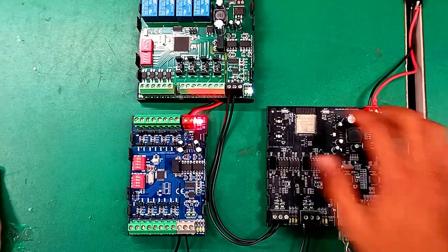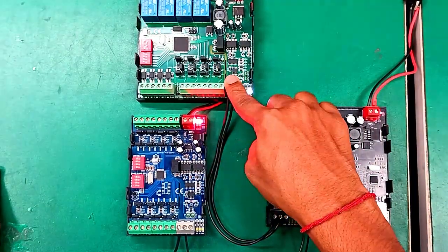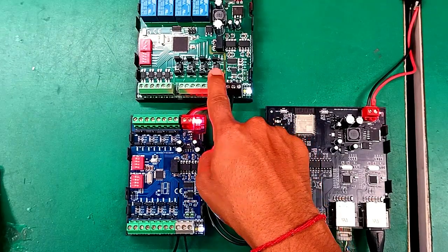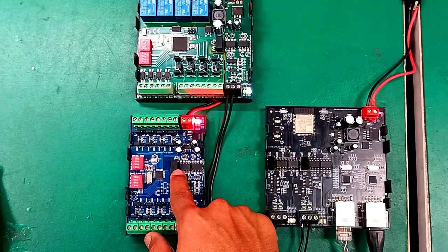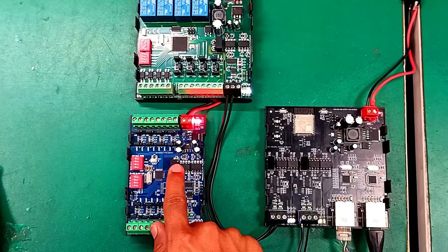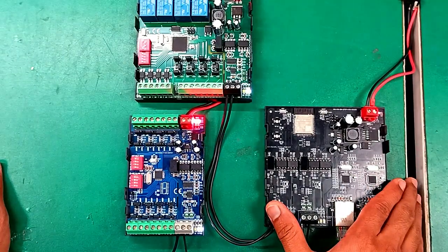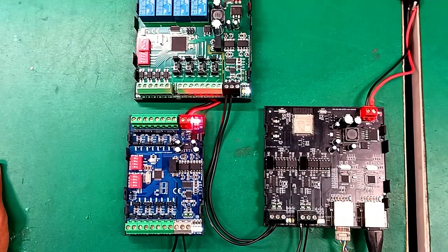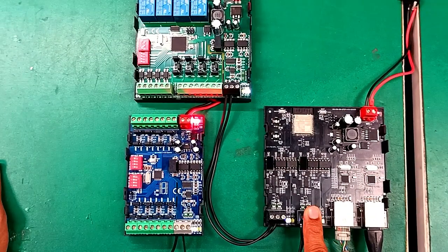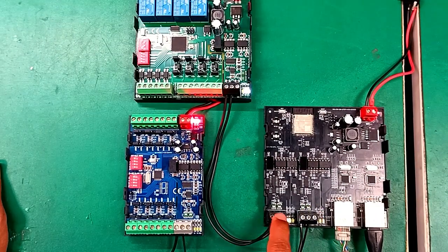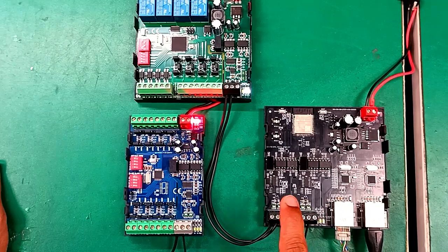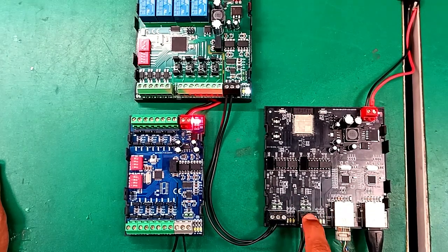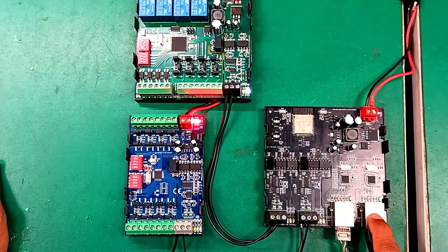So here I have connected two slaves. Here I have slave 1 and here I have slave 2. For this slave I have set the slave ID as 6, and for this slave I have set the slave ID as 1. So here I have the 2M2 TCP gateway. The first slave I have connected to this Modbus, and the other slave I have connected to this Modbus. So the first Modbus data we will get in this TCP, and the second Modbus data we will get in the second TCP.